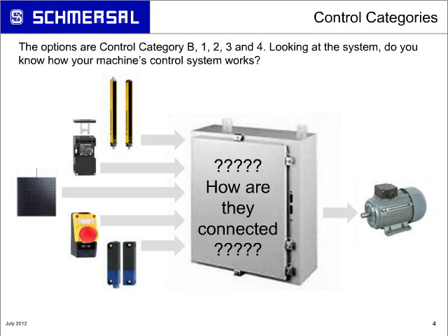You can select the proper safety components: the door switches, the light curtains, your emergency stops, bumpers, edges. In the simplest form, you need to shut a motor down on the machine. There are going to be more details to it, but it could be pneumatic or hydraulic valves that you have to properly and effectively shut down.